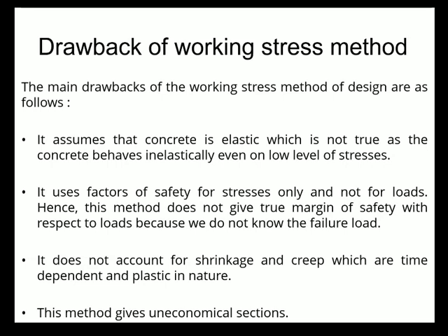Here only one factor of safety, which is typically called the factor of safety in the working stress method, is introduced, but no separate factor of safety depending on the level of uncertainty is used at various levels. So to make the design more rational, it should be taken care of. And then it also doesn't account for shrinkage and creep, which are long-term phenomena.